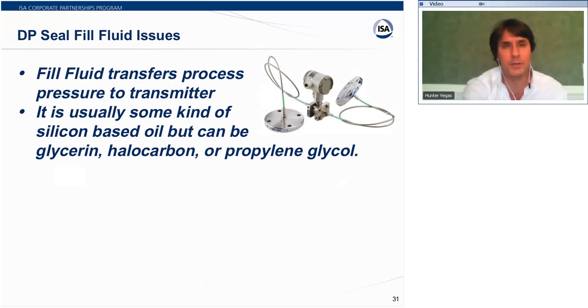The fill fluid can be a source of problems for a whole lot of people, and we'll talk about all that. But the fill fluid itself is usually a silicon-based oil, but it can be glycerin, it can be a halocarbon, it may be propylene glycol. There are some special fill fluids, and they all have their good and bad points.